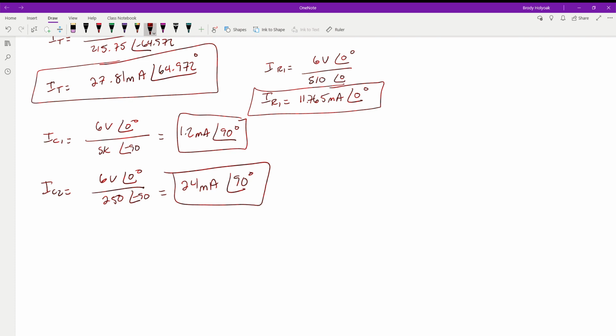And this is how we handle parallel circuits. The next video is going to teach you how to get through series parallel. Now we're going to combine these two methods and just add them together, just like what we've been doing. Again, the hard part is going to be the parallel and keeping those values the same. Just like I said, go step by step. Don't try to skip through things. Make sure everything's listed out in the correct units, and then double check. Do my answers make sense? These things are in parallel. What should the value be? If they're in parallel, the value should be smaller than the lowest resistor. Did I get that? Okay, good, then I'm probably on my way.